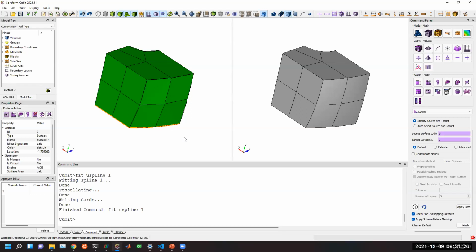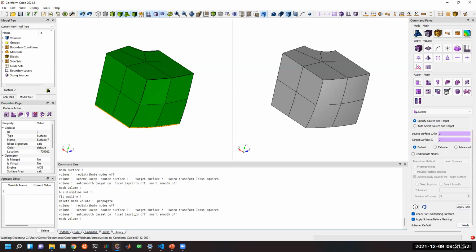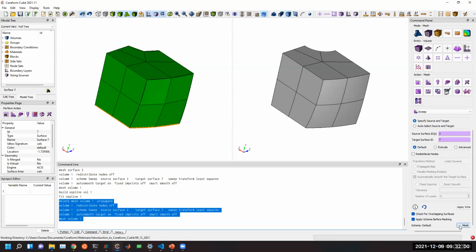Yeah, as we move to a GUI, we see a lot of these are the low level commands that, if you were to see the journal file after running some GUI command panel command, you would see these listed so that we give the user maximum control. But what you can expect is, similar to when we specified this sweep here, there's a workflow to specify this sweep. And if I say mesh this, the commands that actually get issued here, it actually submitted 5 commands when I hit mesh here. And I think you'll see a similar workflow in the GUI that it'll issue these multiple commands that you won't have to memorize. They'll be provided to you through a GUI workflow. But then if you want to see them, to tweak them, you'll have them available to you because they will be journaled. So hopefully that answers your question, Clint. It's a very good question though, and thanks for asking it.